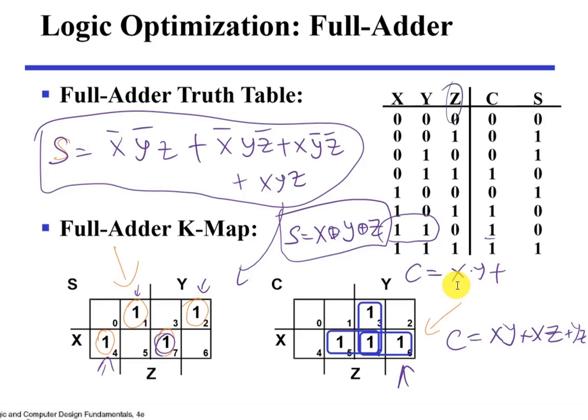Okay, so we can write it down, x exclusive or y, right? And then z. Okay, so we know that the exclusive or truth table is such that if x and y is different, right, then we have output 1. And if this is different and then we have z is 1, then c will be 1. I mean, c will be high.